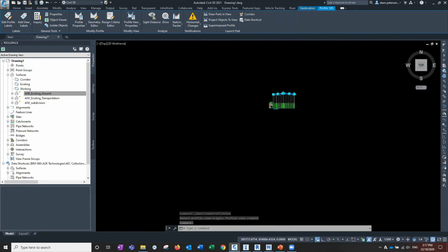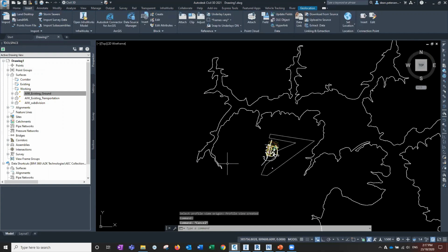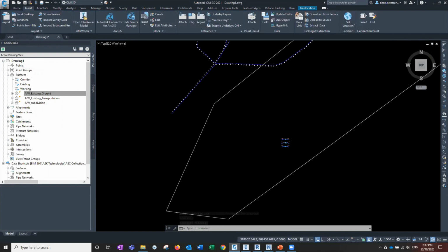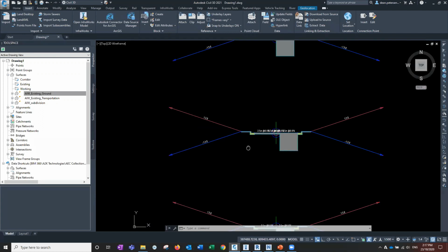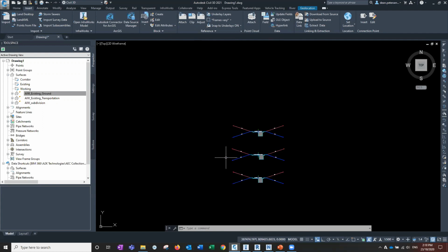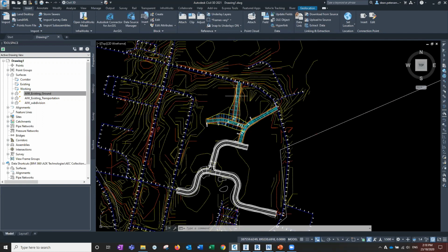So these are all good starting points for where you can start doing the detailed design based on what you've sketched. There's also a bunch of assemblies in here. So that's the intentional mistake. These are not full sub-assemblies, so you want to swap these out, but they're a good marker, a placeholder for when they come through from Infraworks, and then you replace them with full ones to do your full design. So that's all good, and we can do the rest of these as well.